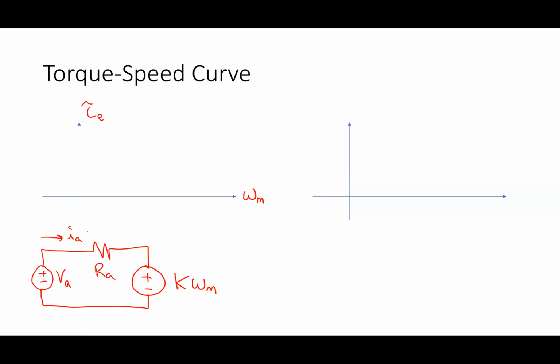If you're close enough, you can see it. Right now I've got 2 volts on this, and it says it's drawing 0.16, 0.17 amps. If I grab the shaft, the current should go up. And it did. It is basically maxed out now at about 0.8 amps, because the power supply can only provide 0.8 amps in the setting that it's in right now.